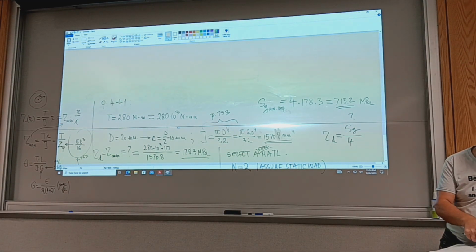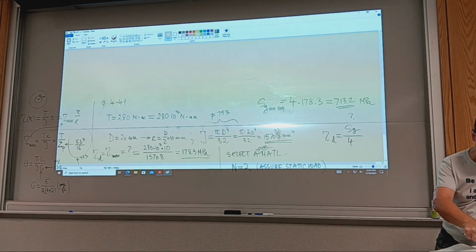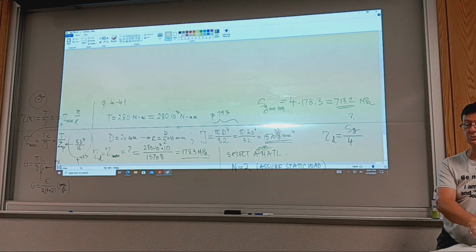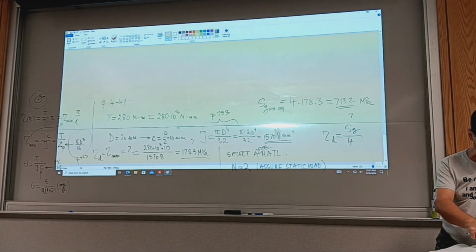We look at the column for SY, and as you go down, you start seeing the first carbon steel, 1080 oil quench and temper 700. Shall we go with that one? Those are high carbon steels, used for tools, chisels, and files. So no, let's forget about that.